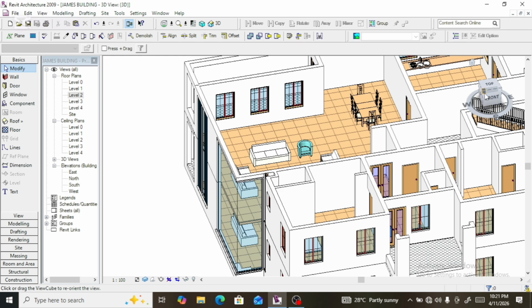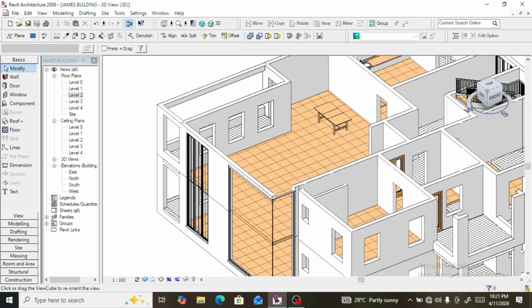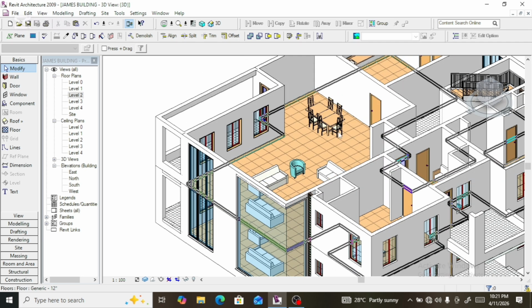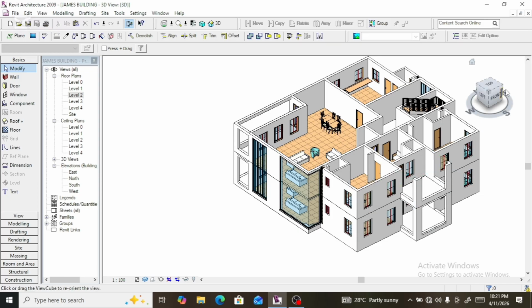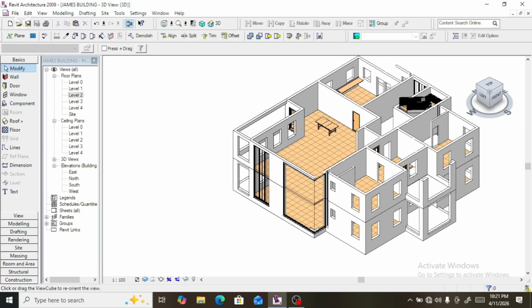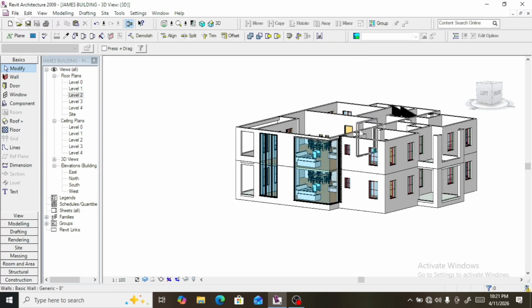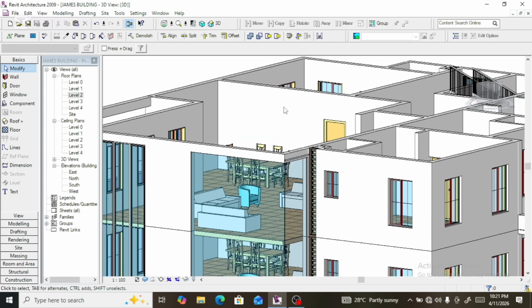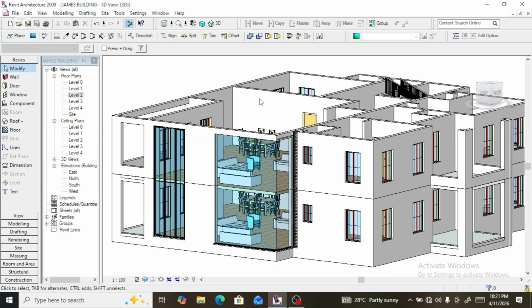We can collide both of them at the points so it will look accurate and good like this. There's always a way to achieve this when the material you imported is giving you difficulty in alignment. You can create a different wall to make an adjustment. So therefore we have achieved that, and the windows and the doors are okay.